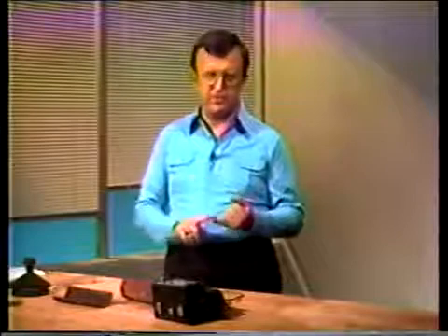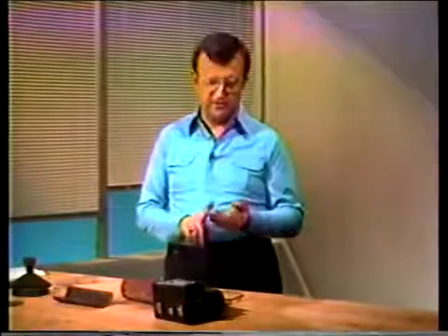A waterside inspection does not end at the drum or moisture separators. Headers and tubes also have to be inspected. Headers and tubes are subject to 5 general problems: erosion, corrosion, deposits, cracks, and problems with welds.